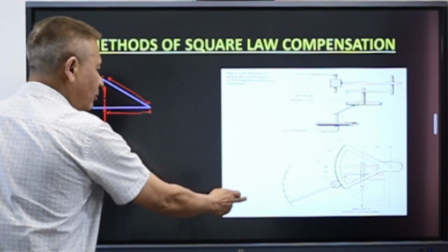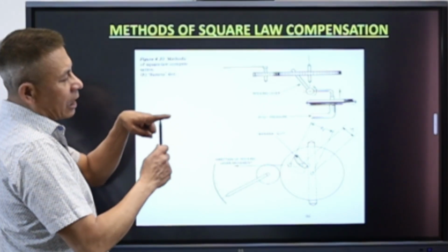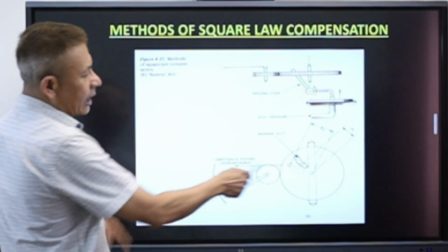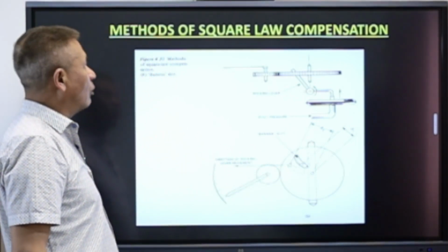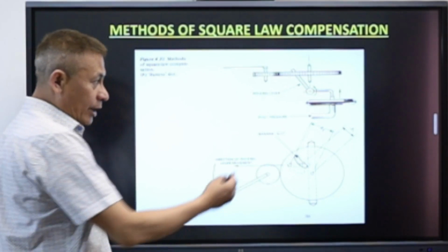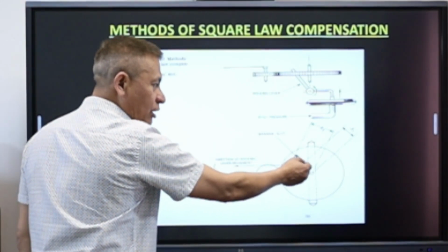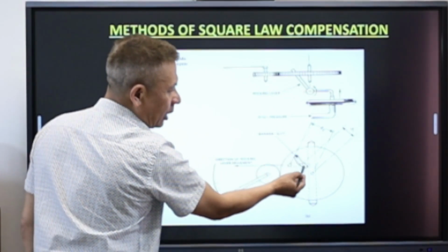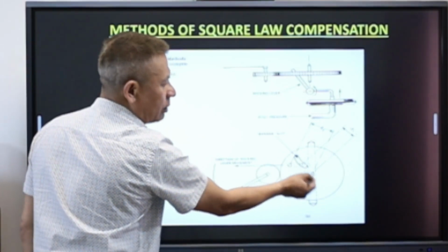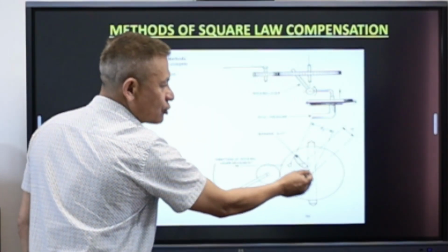Another mechanism which is commonly used in aircraft is that instead of having a mechanism like this, in a particular dial, there will be a slot which is generally known as the banana slot. When the speeds are very, very low, the push onto the needle is going to be effected from this particular area, which is a short arm.